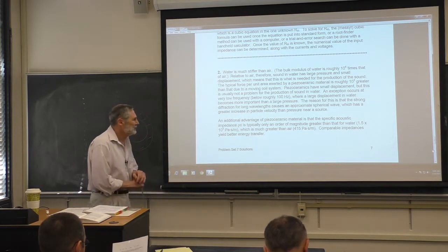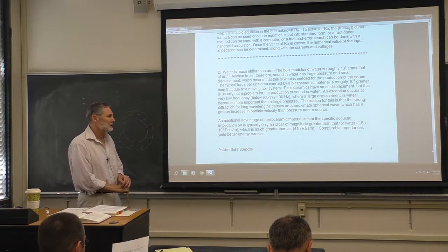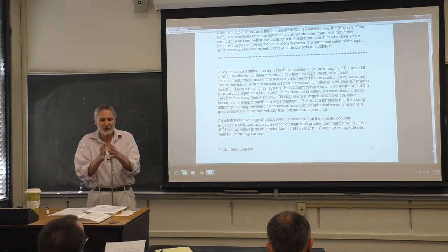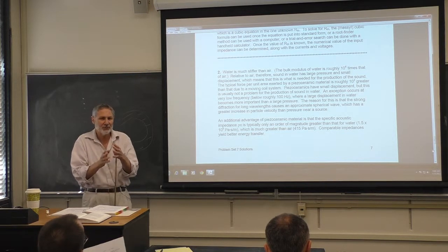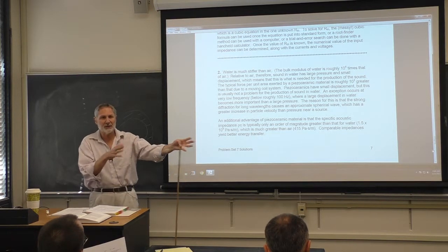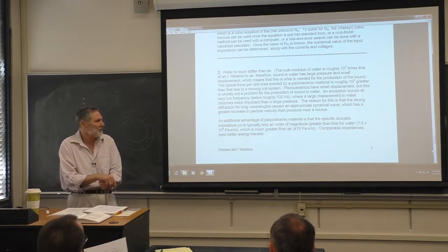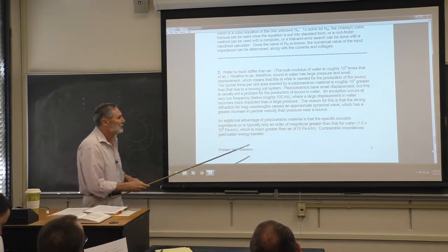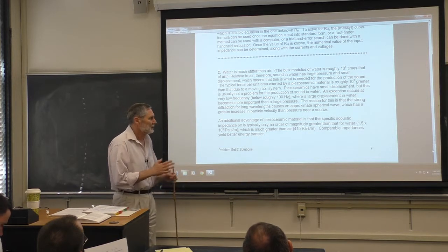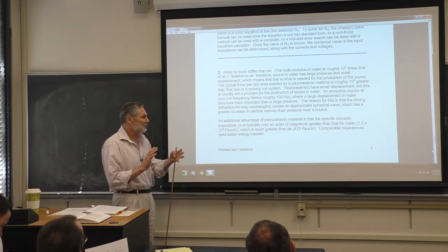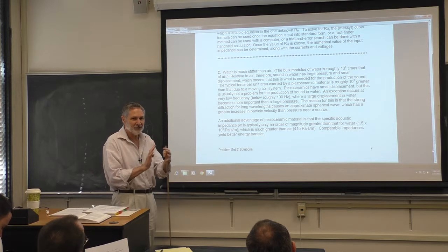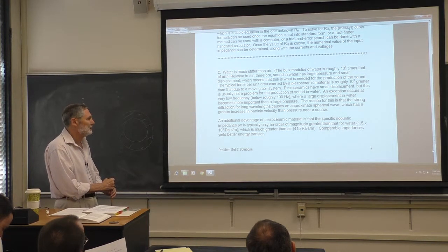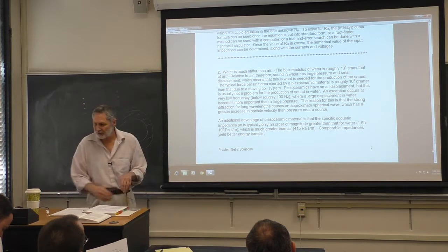Now there's another way you can look at this. The material that you have has some specific acoustic impedance, and the fluid has some, and you want to match those as best you can. So clearly, the solid's going to be a better match than any kind of underwater loudspeaker, right? So you want comparable impedances to improve the energy transfer.